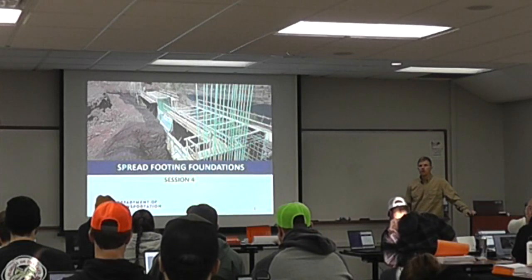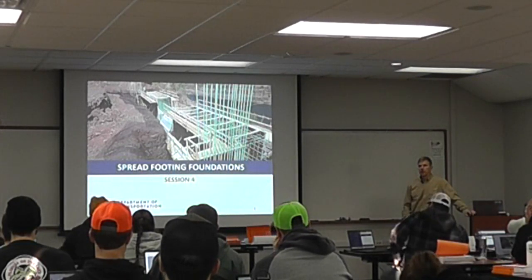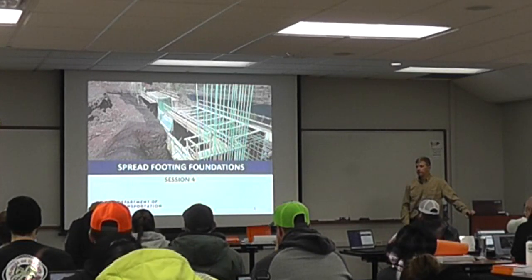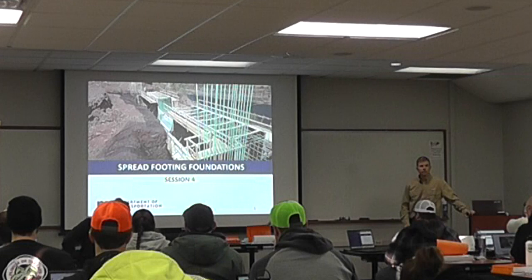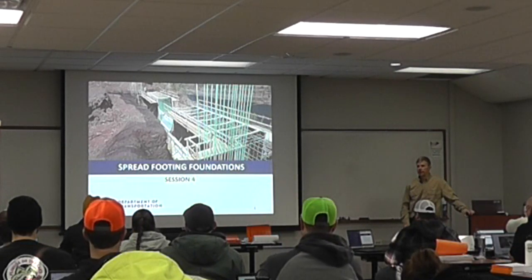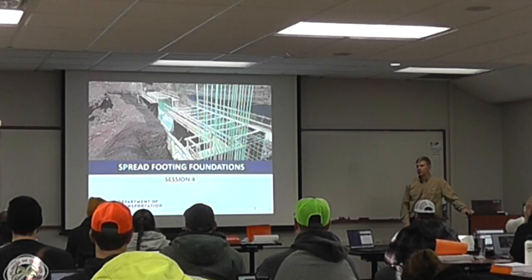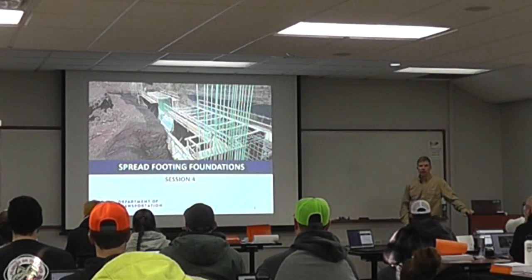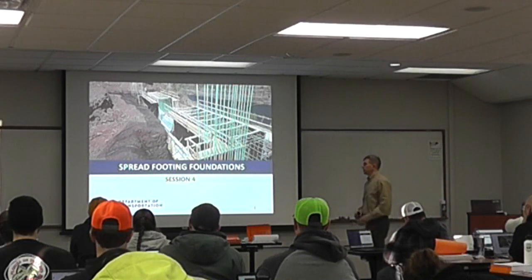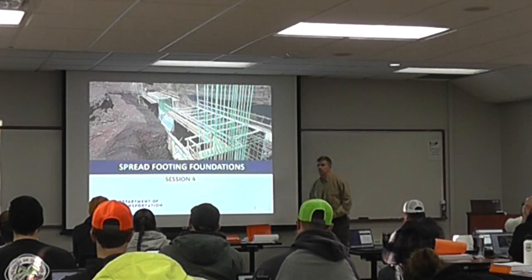Bedrock. Very solid. It's been there. It doesn't move. What else? Gravelly granular, especially if it's dense. There could be some sands that get kind of soft and whatnot. Yeah. So those are a couple of perfect examples of where we would use spread footings.